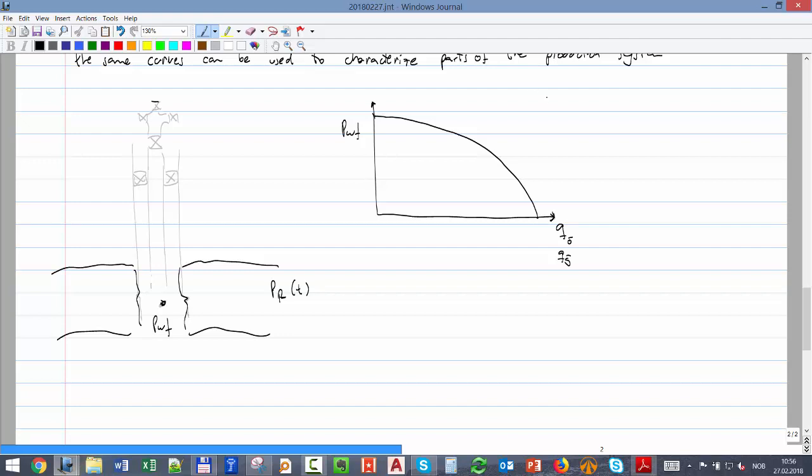So how do we call this curve? IPR, inflow performance relationship, which petroleum production and reservoir engineers like to use very much. And it tells you that if I fix somehow magically this pressure, PWF asterisk, at the wellbore, I'm going to get that rate.